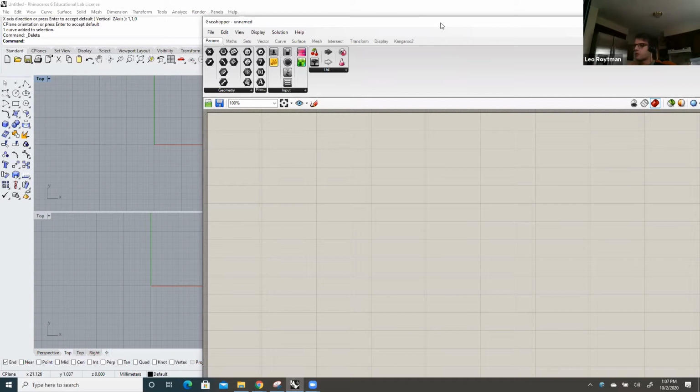For example, in 3D Max, you take a geometrical object like a sphere or a box, and then you apply a sequence of modifiers to it. Your final object in the model is the view of this first object with the whole stack of modifiers applied.